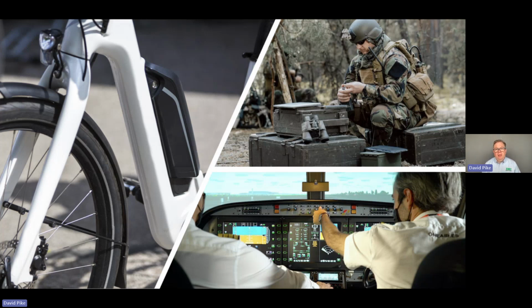But the picture on the left there is an e-scooter, an e-mobility device, the latest generation of battery-powered vehicles that you see across towns and cities around the world. A combination D-sub with its ability to deliver both power and signal is finding its way into some of these new trends and these new applications. With a single connector being able to provide all those functions, it makes maintenance very straightforward. And so you'll find D-subs encroaching into some of these newer industries that you might think wouldn't be the place for a traditional connector like a D-sub.